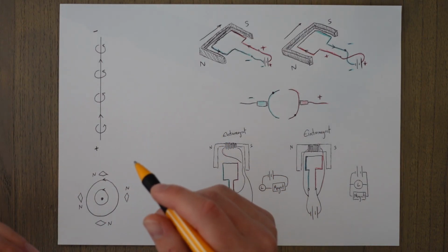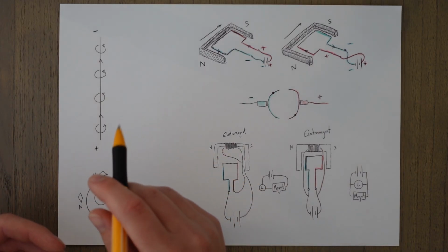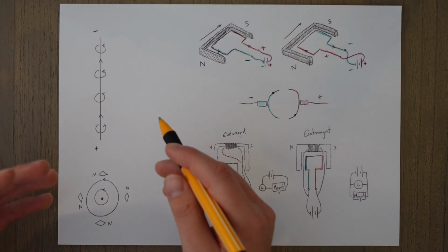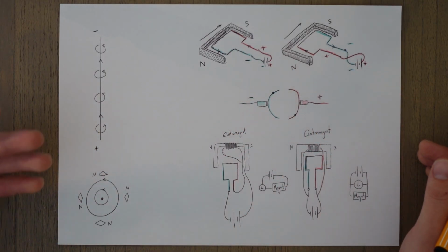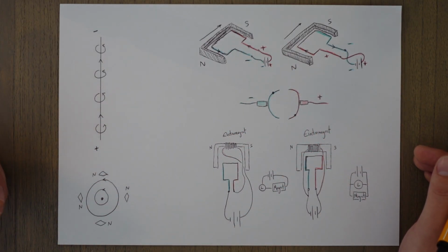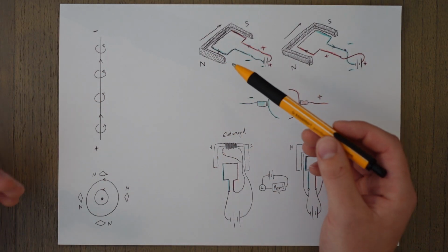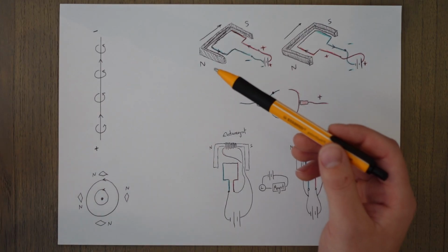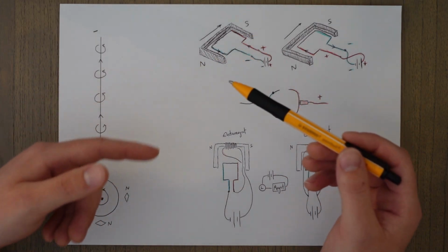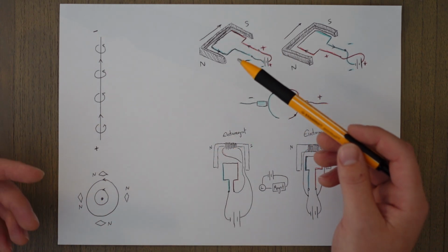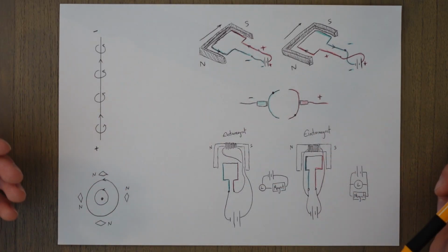And we can use this electromagnet created by the current through the wire to attract and move other magnets, maybe to push a switch or move a valve, which is sometimes referred to as a solenoid. If we take our wire with current flowing through it and place it next to a stronger stationary magnet, then the two magnetic fields, one by the magnet, one by the wire, will interact with each other. And this will cause the wire to move, just like if you put two normal magnets next to each other.